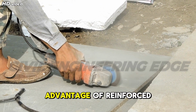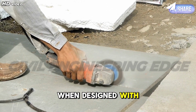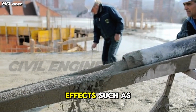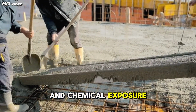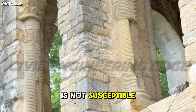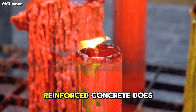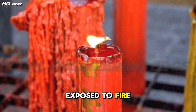Durability is a major advantage of reinforced concrete columns. When designed with proper cover, quality materials, and correct detailing, they can resist environmental effects such as moisture, temperature variation, and chemical exposure. Compared to timber columns, reinforced concrete is not susceptible to decay, termites, or fungal attack. Unlike steel columns, reinforced concrete does not rapidly lose strength when exposed to fire.